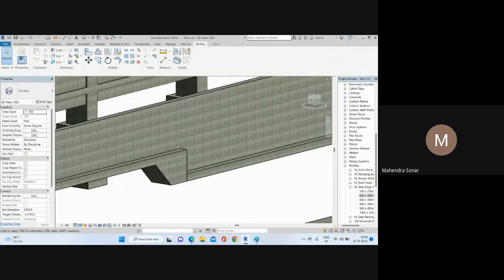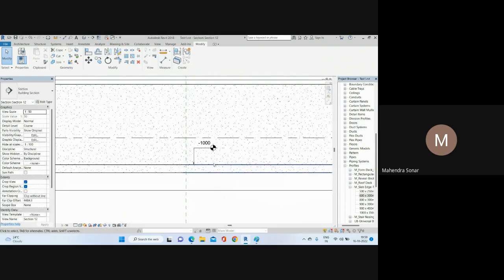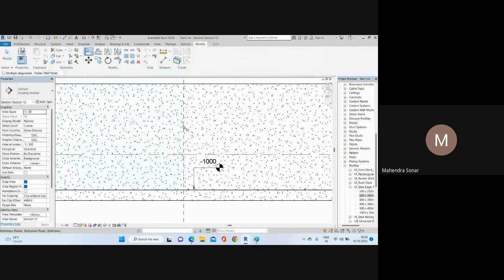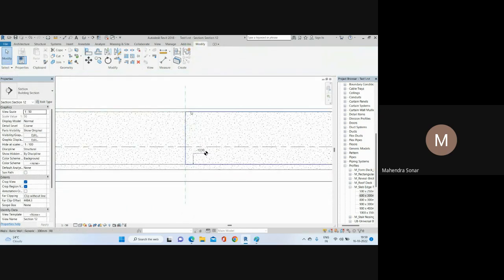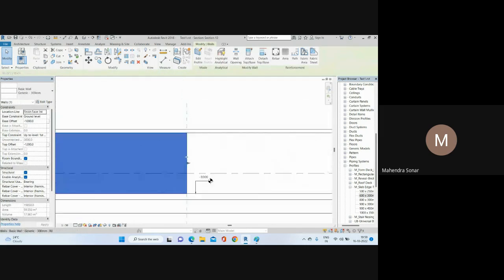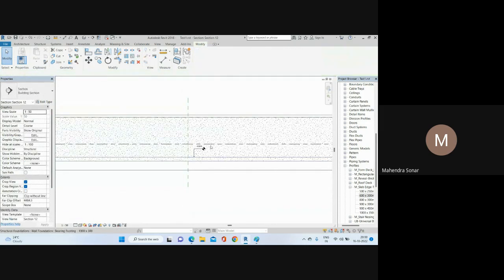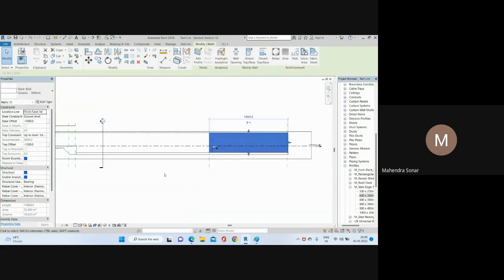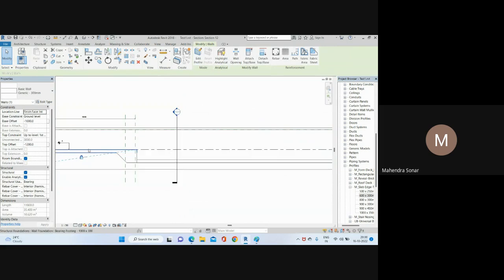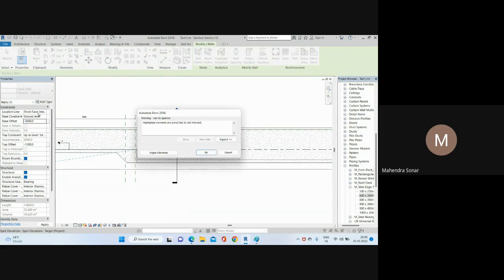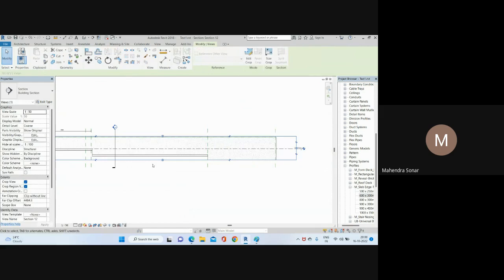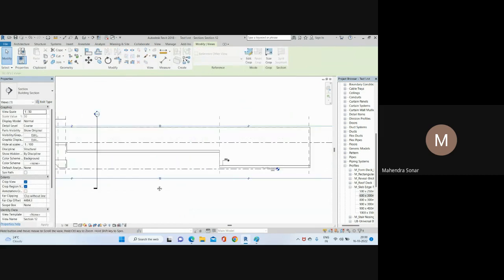Okay, you can go to the elevation here, right? So this is your wall here. What I do, I will give the align command and extend up to here, and you can see the exact step location here. After that, for this wall, consider this wall is going down 3 meter from here. So you can add 3 meter from ground level and click here. If you extend this viewport, your wall looks like this.